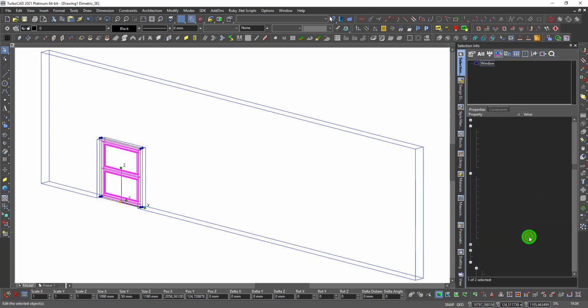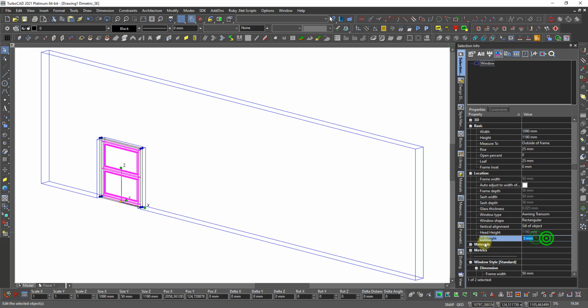But if I set it as sill of object, I can say minus 50 or 500. That's a little thing that's good to know, especially when you're making a garage. It works the same way on a door. Because then we maybe have a 30 centimeter concrete wall before we put in the garage on top of it, and then we want the door to go a little bit down in the concrete. Then this is good to know. If we put it on sill, you can go below.